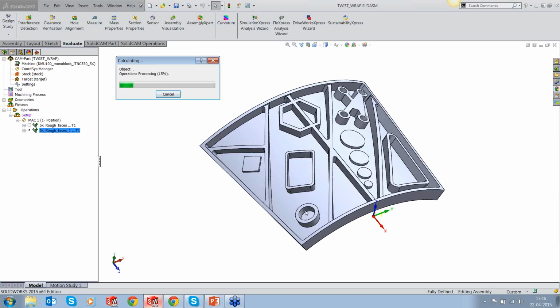If it is doing around here, it will spiral inside the circle. But if it's outside here, it will take the outer contour and the inner islands into consideration before creating a spiral. And the same goes for the island over here and also the pocket out here. So it will create a pretty interesting toolpath which will mimic iMachining but in 5-axis.